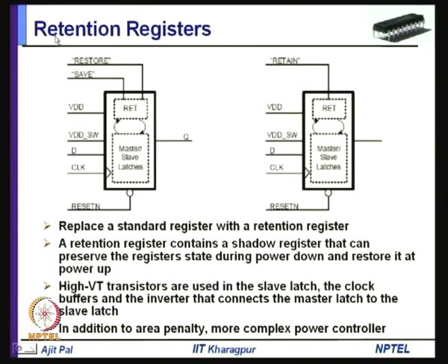Third approach is based on retention registers. As I was telling, you can have built-in hardware present inside those blocks. What is being done is you have two sets of registers, one is master, another is slave. Whenever a save signal is received, the information is transferred from the master to the slave. And whenever a restore signal comes, the information is transferred back from the slave to the master.